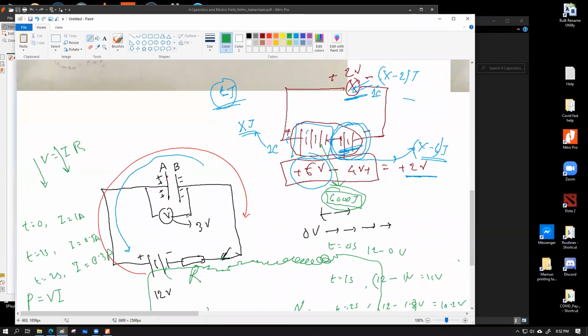Let's say at some point, this voltmeter is giving us a reading of 12 volts. This means the total amount of effort this battery is trying to make the clockwise current is exactly equal to the amount of effort this capacitor is trying to produce an anti-clockwise current. These two efforts, or these two opposite EMFs, are going to cancel each other out, and there would not be any resultant current in the circuit.